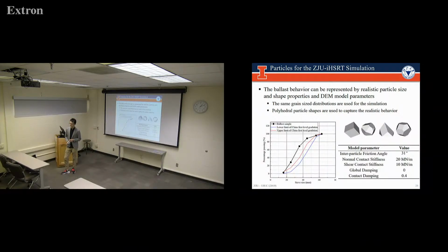So we know that's what's happening. Why not pick certain locations, let's say a 10-year life cycle or a 20-year one, take the different gradations at different stages of life, and look at the deformation behavior of the different compositions, right? Bring them all together to understand it. So that's kind of where we're moving towards. Early on, we got many questions on this approach, like, oh, but your DEM approach cannot break particles, right?